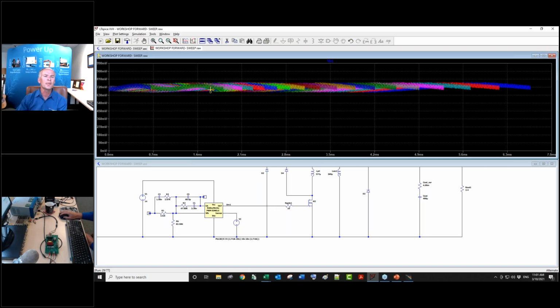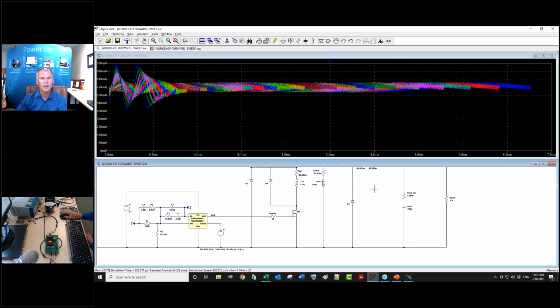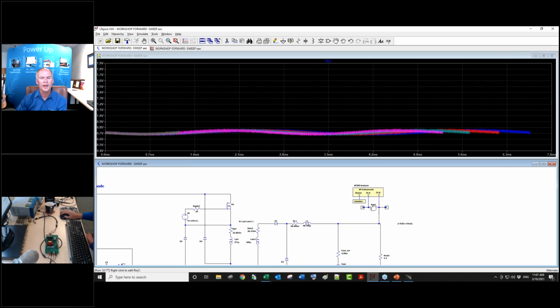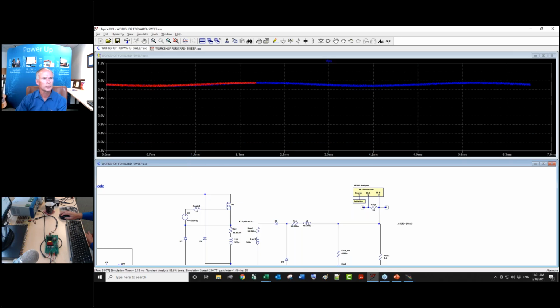So now we see the problem in this loop. We see we're getting more and more modulation on the output of the error amplifier, and we're going to hit a point where this signal gets too big. We're injecting the same size signal, of course, across the resistor here. This one is shrinking, channel B is growing, and then channel C is growing even more because that's getting amplified by the feedback amplifier. Growing and growing.